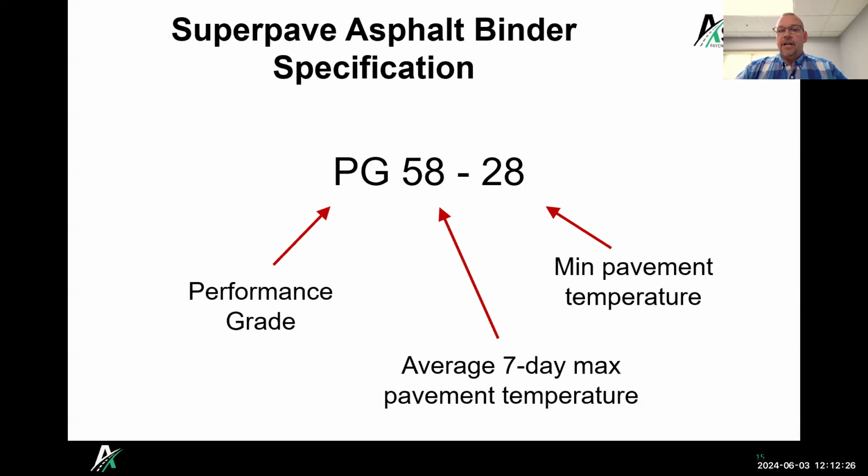So in an attempt to reduce the number of mixes that we're producing here in the state, we originally wanted to go down to 3: low, medium, and high volume. MDOT wanted to keep 4 of them, so that's where we ended up. In some ways, it really is kind of like 3. The EH doesn't get used that often here in Michigan, because when we get up to those higher designations, a lot of times MDOT will specify an SMA mix, a stone matrix asphalt mix. So we feel like we've gotten down.